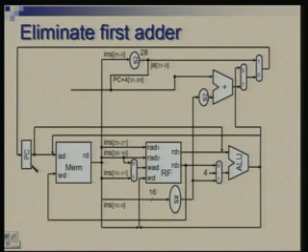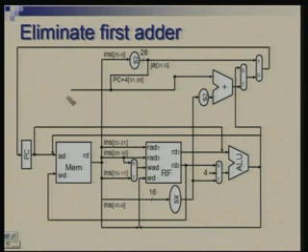Since it is a multi cycle design, PC plus 4 would be done in a particular cycle, and that value will be put back into PC, because remember that we are going to put all values into some storage element, some register, at the end of the cycle. So, that resource which computed that becomes free. So, this input here will come from PC now. I simply make that connection there. So, we have taken care of removing the first adder.